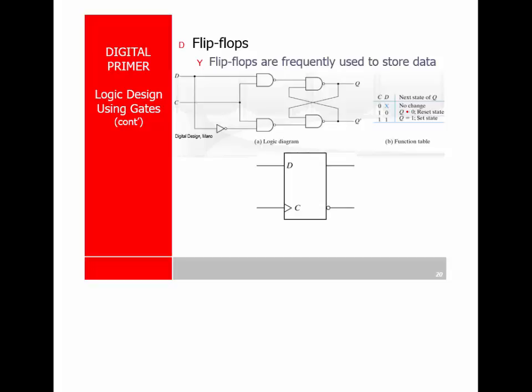That we're using this as a clocked input right there. So, right there. And all this basically says is that whenever the clock rises, on a rising clock edge, whatever is on D is then just moved out. And it stays there until the next clock edge.